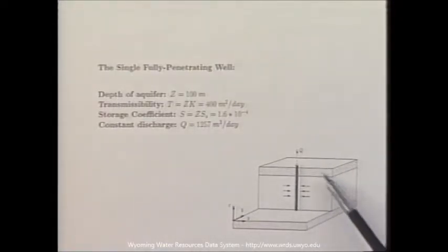If I didn't use the finite layer method and just simply solved the system, or if I didn't have orthogonality, I would have 900 modes, and I used only one layer, so there's nodal plane 1 and nodal plane 2. I'd have ended up with approximately a 2,000 dimension linear system.